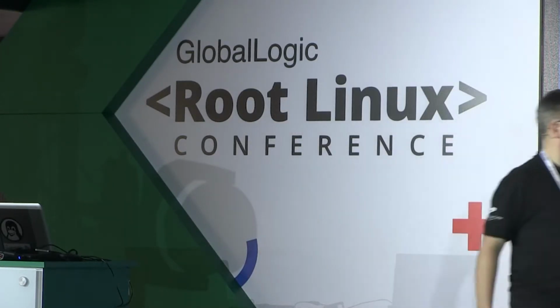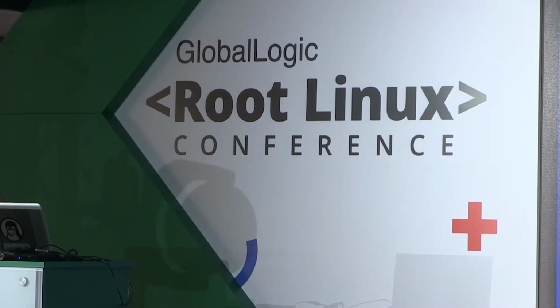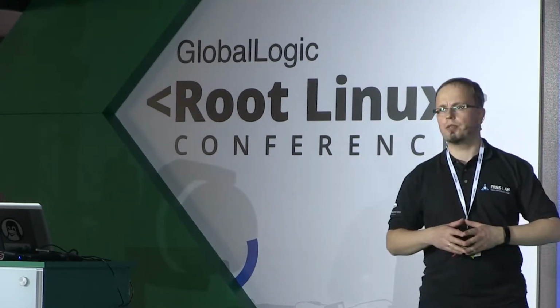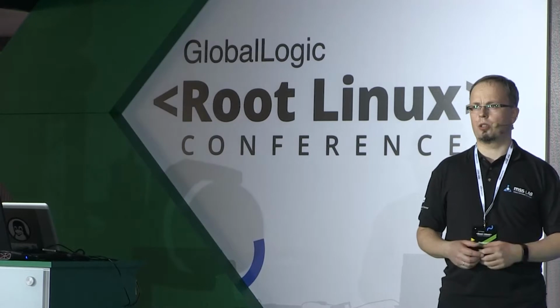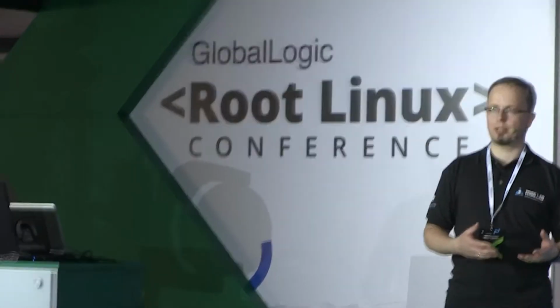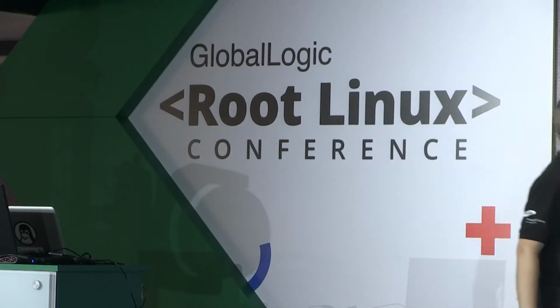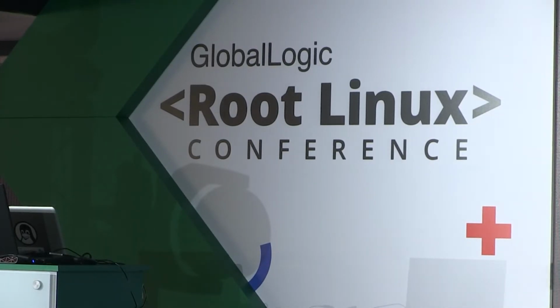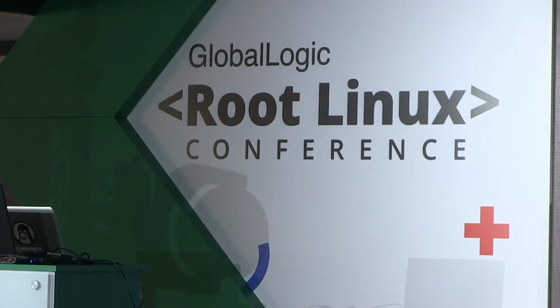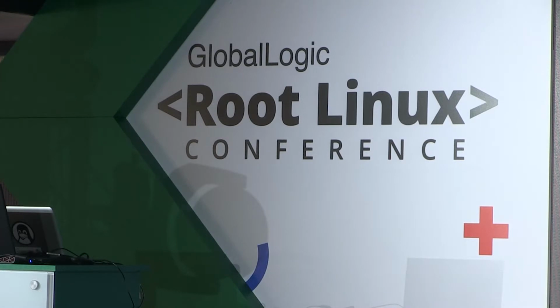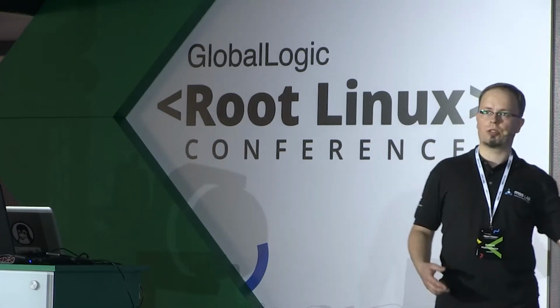Under the mount point of each function.fs instance, there is an EP0 file, which will be used for receiving control events from the host, but before the function is active, it will be used to write USB descriptors and strings to the kernel. The kernel then verifies those descriptors, and if it can handle such a request, it creates the appropriate number of EP files according to what was in the descriptors. Then we read and write the appropriate files, and this way we transfer data from the host or to the host.